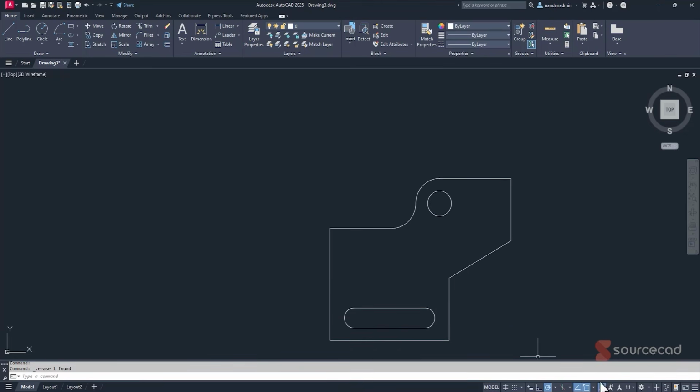Now you might be wondering, if it's so useful that it can show all the points that we need for making a drawing, then why don't we just keep it active all the time? Well, there is a reason. If you activate all of these points, then the points at close proximity will all highlight. And at some point you may end up making mistakes, say, if you want to add an intersection point and then you end up selecting end.